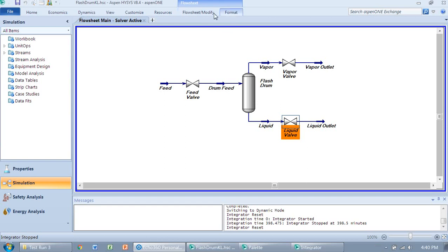You can verify that by clicking on format flow sheet modify, and then you go into the dynamics PF specs on the right, the most right down selection, and change from default color scheme to dynamics PF specs. If you see the green line going to the feed well, and the light blue becomes the drum feed, that means you have already switched to the dynamic mode correctly.